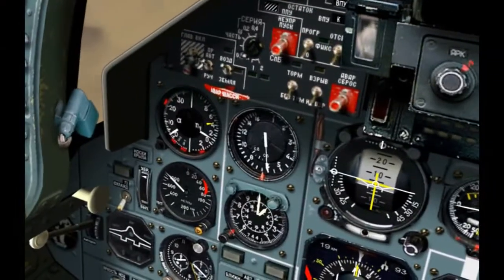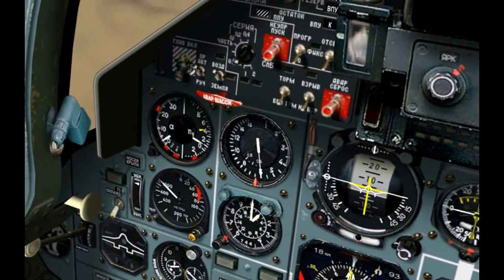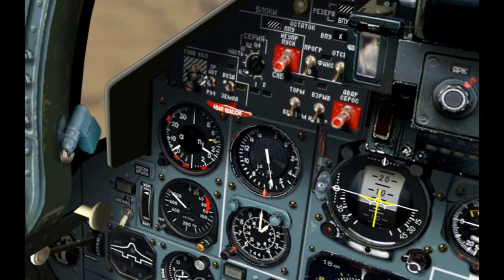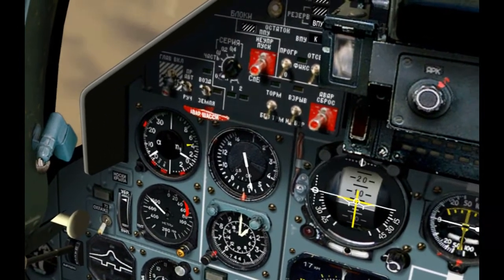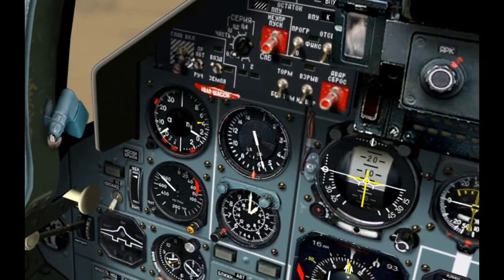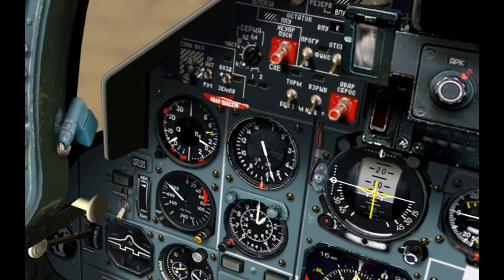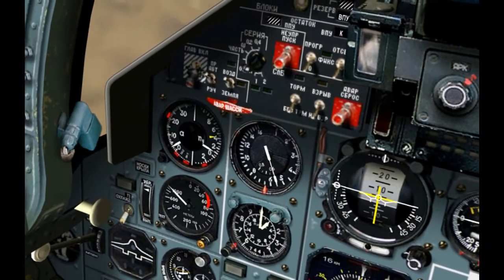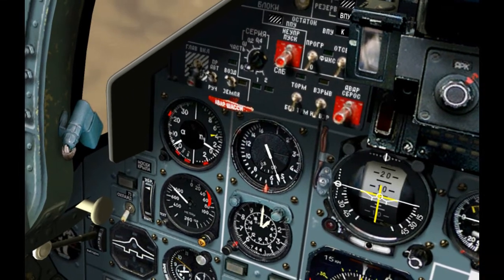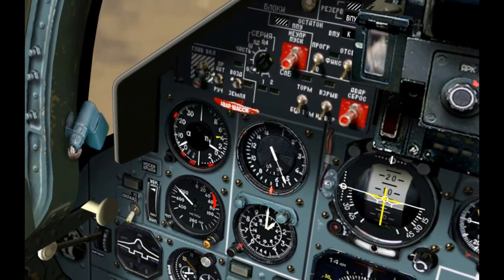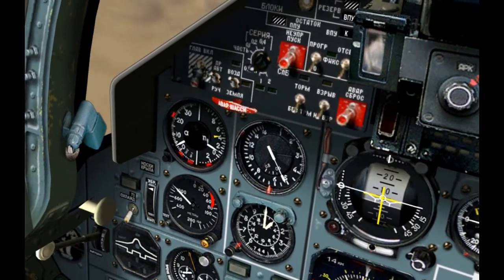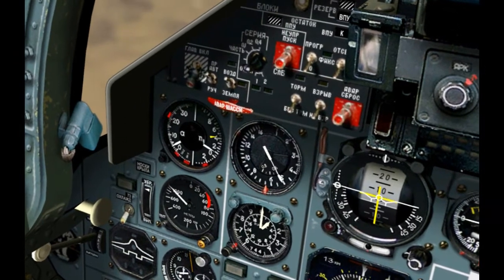Let's have a look at these 4 lonely gauges over here. The upper left, we have the angle of attack, represented by the Greek letter alpha, as well as the number of G's being pulled at this moment, as well as the maximum number of G's we pulled in this flight. So you can see we've pulled 4.5 G's on this flight so far. To the right of that, we have airspeed, with the inner ring showing current Mach. Right now we're flying at 525 or so kilometers per hour and at about 0.6 Mach at this altitude.